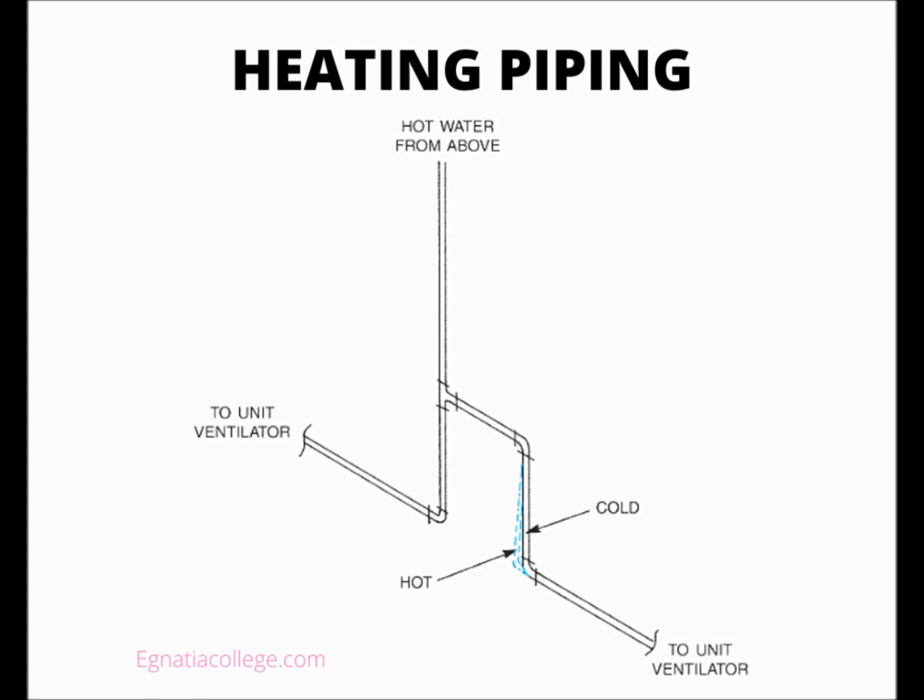If we continued on to the right or north, we would come to construction note 2, which tells us that the symbol indicates a riser to the second floor. The riser is not shown in the wall, where it would actually be positioned, because doing so would bury the riser symbol in the wall with material symbols and other lines. The pipe going down is actually shown at an angle up and to the right. This is the isometric portion of the drawing.